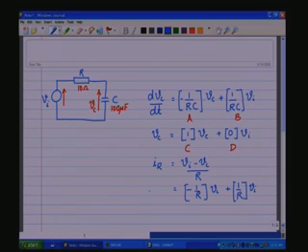This is the modified output equation, where now you have to give this as your C matrix and this as your D matrix, not this. So, if you want to see IR as the output, we have to give this as the C matrix and this as the D matrix.